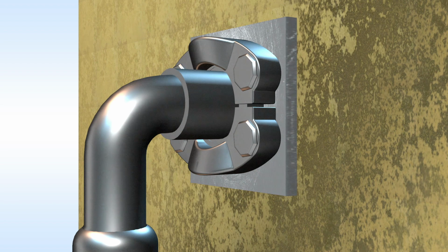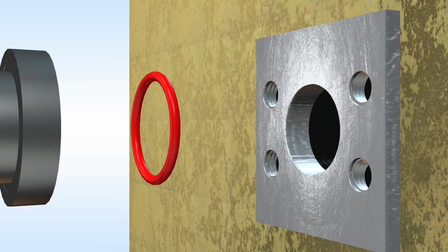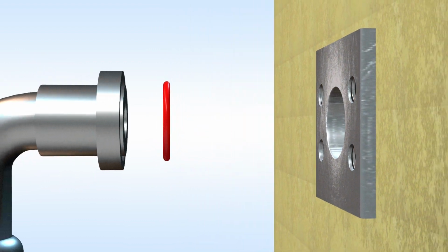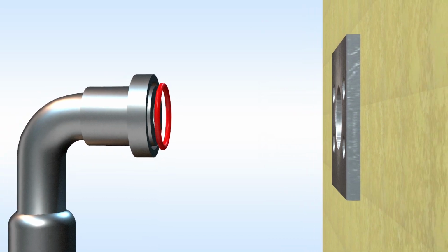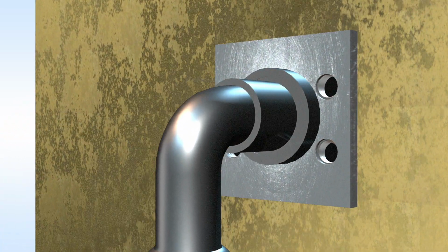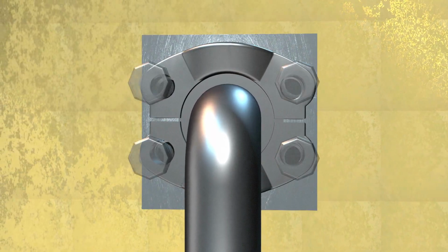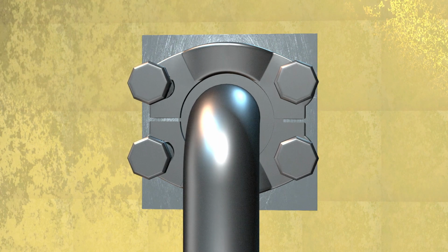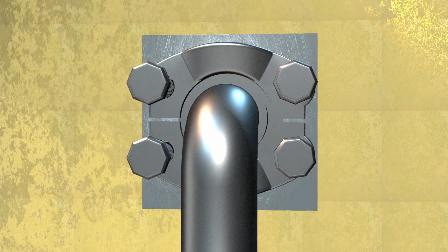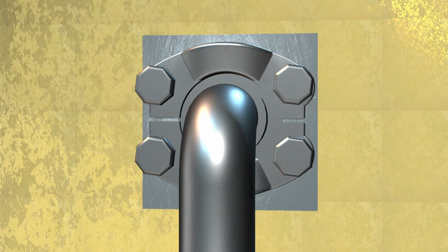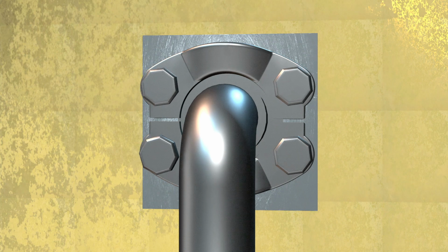The correct installation of the flange is as follows. Inspect all components for damage or contamination, particularly at the sealing faces. Install the correct O-ring in the flange groove, ensuring the O-ring is not twisted. Lubricate the bolt threads. Align the flange and the two clamp halves to the port. Install the 4 bolts, hand tightening evenly to seal the O-ring on the port face. Torque the 4 bolts, alternating in a diagonal pattern to about 80 to 85% of the final recommended torque. Finally, torque the 4 bolts, alternating in the same diagonal pattern to the final recommended torque.